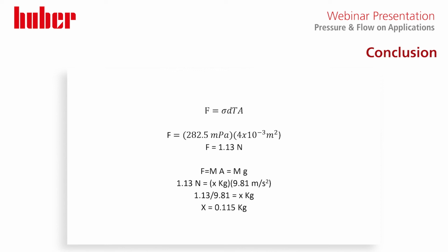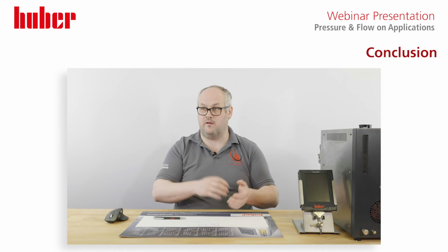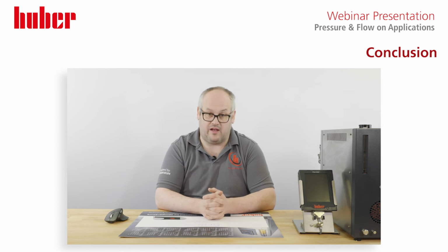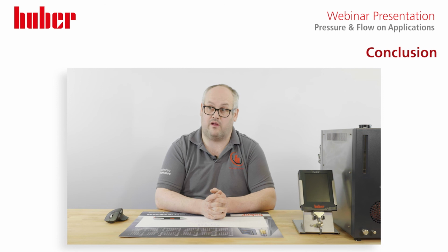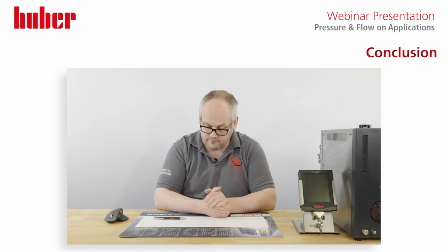So really, it's like putting a large apple on top of our glass reactor. That's the kind of stress being applied by the temperature increase. So that tells me that I'm not working over enough of a temperature range to shock the glass. If I was working over maybe an 800 or 900 degree delta T, we might be in the range of applying stress to the glass that would cause it to rupture. But bear in mind, they do anneal glass in ovens, so it does take a fair whack of a delta T.